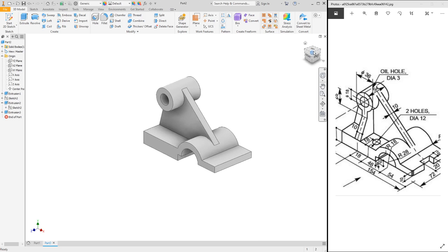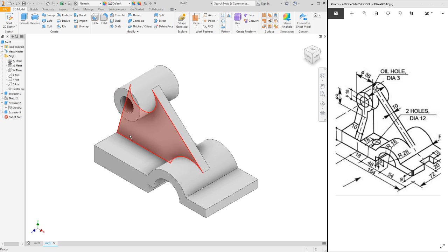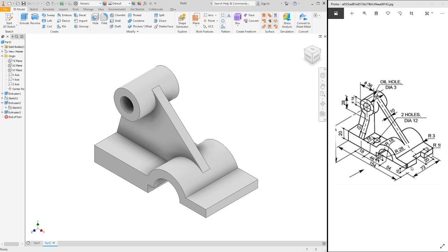So we have to create a sketch. All right, so to create a sketch for that one, the sketch has to be along the center of this hole here, at the center of it. All right, so we have to create a plane there because there's no plane. We create a plane there to create the sketch. And we know that the distance from the face here, that is this face of the object to the center, has been given to us as 18 plus 46 plus 54. So we have to create a plane at a distance of that from this side here in that direction.